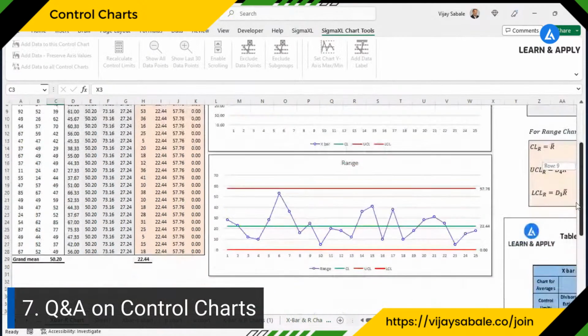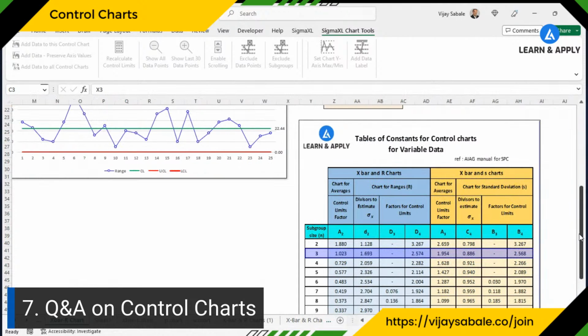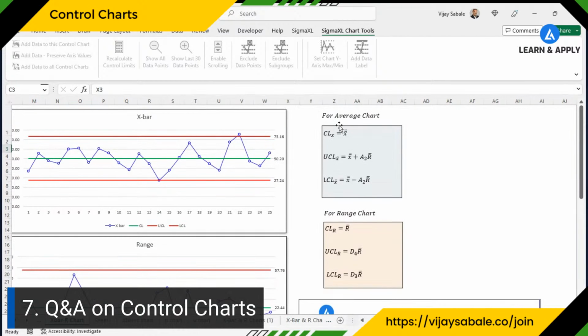Here it is. So we can see, based on the subgroup size, the constant we are going to select here, whether it's X bar R control chart or X bar S charts. Let's go into the formula. For the average chart, the center line is X bar, that's the average, X double bar. The upper control limit is X double bar plus A2 into R bar. Now what is A2 here?